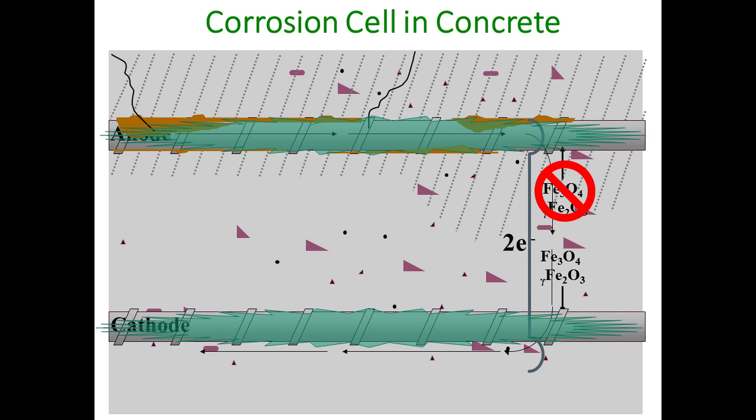But over time, what ends up happening, in this example, could be de-icing salts, it could be chlorides from a marine environment, but whatever it is, we're going to have some contamination that occurs over a number of years. So the chlorides penetrate the concrete. They make it to your first mat of steel in this example, and what they end up doing is breaking down this protective layer, this passive oxide layer, that you have around your reinforcing steel.